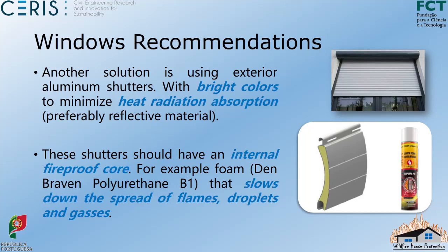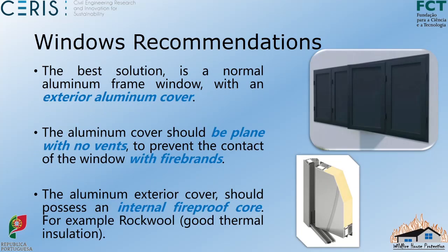Another solution. I understand you might not like the previous solution, so I'm going to the first solution again. Remember, the first solution is maybe the most expensive one, because we know aluminium is quite expensive. Once again, this is the best solution. I'm going to present another solution. This solution prevents the contact of the flames with the window, and also prevents, remember, it's not only a problem of the flames of the burning trees that are in contact with the dwelling, it is also the problem of accumulation and projection of firebrands that go in contact with the window, may break the window and produce an interior fire.